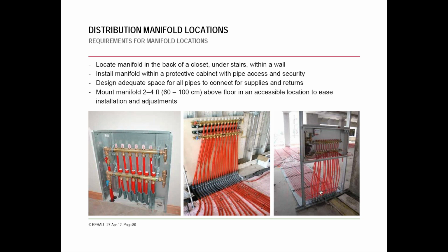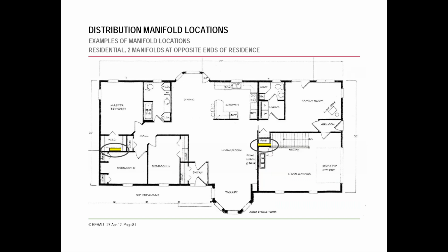Regardless of the installation type or brand, you're going to want to run all your piping through PVC sleeves when it comes up out of the slab, just to protect it long term from anything rubbing. Here, as you can see, if you can keep them nice and neat and lined up with a piece of unistrut or otherwise, it definitely makes installation easier. It makes anyone that comes after you working on it a lot easier as well to diagnose. For example, if one loop seems to be leaking, it can be shut off and addressed, or if you need to change the flow to a specific area.